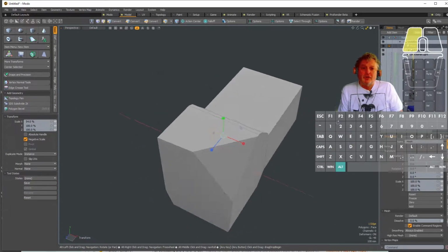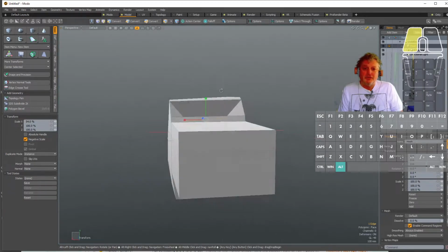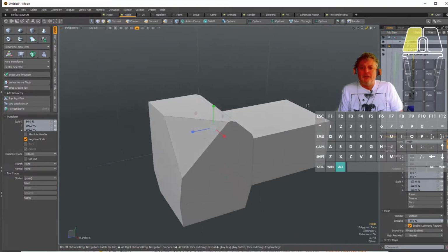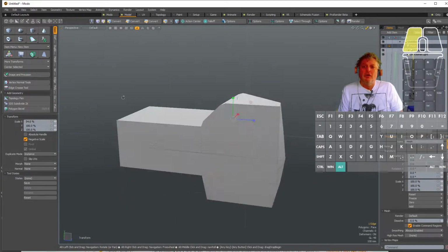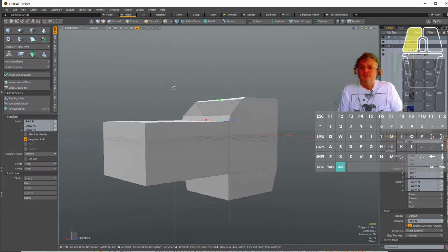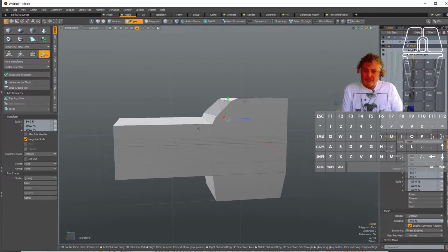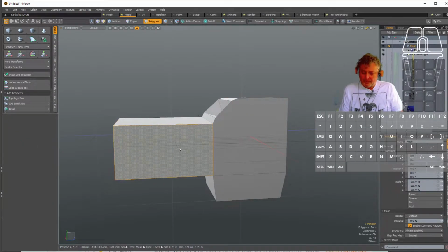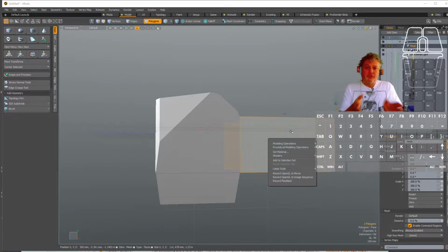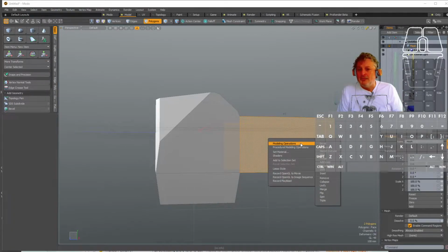I'm getting close to something that is pretty valuable here, which is called bridging. Bridging is a way to connect polygons or to put holes in polygons. I'm going to select two polygons, hit the 3 key. I'm going to select this polygon, and this polygon. And I'm going to right mouse click them, and notice they face away from each other. And I'm going to go to bridge.